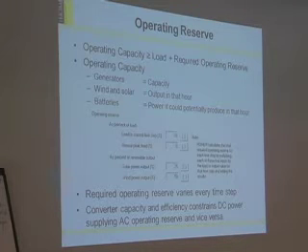So a couple of things we don't consider. We assume if the generator's running, it's capable of ramping up to its maximum, to its rated capacity. So we're not considering ramp rates. Now, if you're thinking about hour time steps, that's I think a totally defensible assumption. When you're running Homer at a 1 minute time step, you're starting to get to where ramp rates might be important, depending on the generator. And if you're trying to use Homer to look at a coal plant, well, that's an issue. But people don't generally do that, so that's fine.